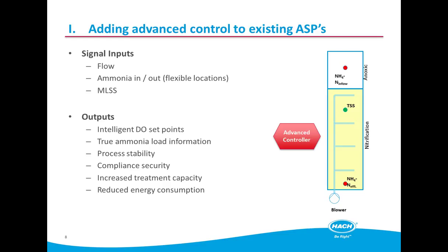So yeah, it's not a rapid answer, I appreciate that, but the nitrification controller provides the right level of treatment for the biology that you've got. The sludge age controller manipulates the biology you've got to give you optimum conditions. So with a standard upgrade minus sludge age control, you will ensure compliance of the plant by applying the correct amount of dissolved oxygen.